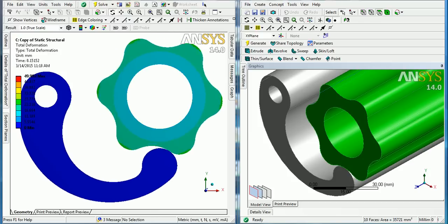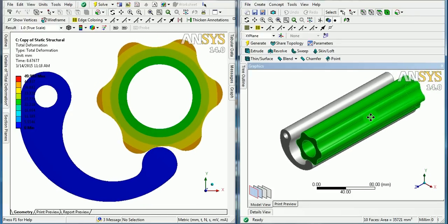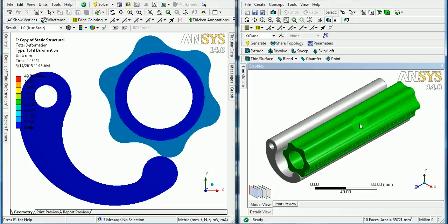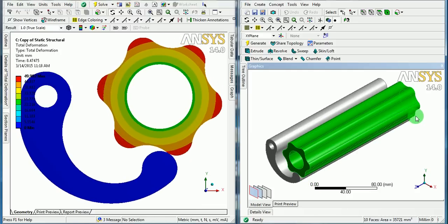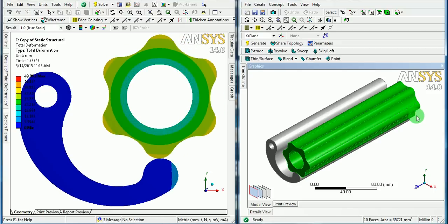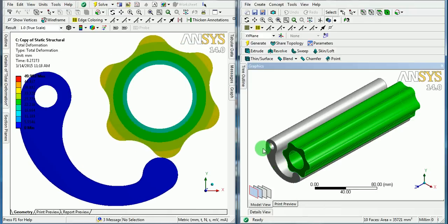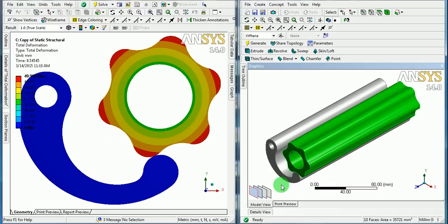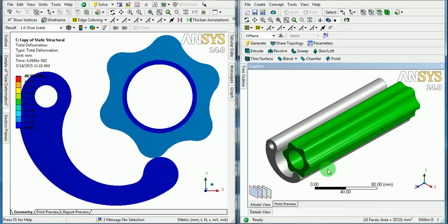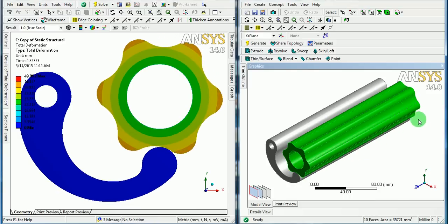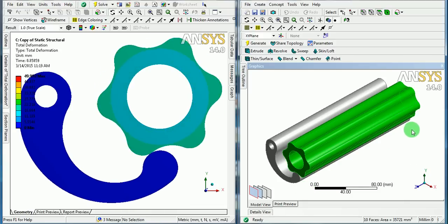The condition for the plane strain analysis is when we have a mechanical structure whose length perpendicular to the xy plane is larger in comparison to the dimensions in x and y. Also, the loading is perpendicular to the z-axis and uniform throughout the length.